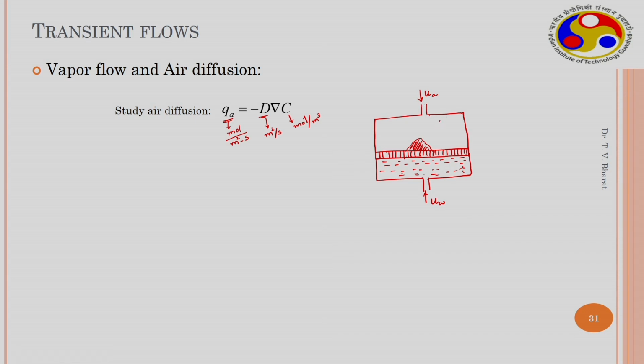So, here there is an air pressure that is maintained, and here water pressure is maintained. Generally this air pressure is very high, higher than the atmospheric pressure. So, due to the water pressure that is exerted, you maintain a UA minus UW pressure, that is suction, that is controlled within the chamber, because water pressure is UW and this is air pressure. Generally this water pressure is equal to the atmospheric pressure, that is 0 if you consider it to be gauge